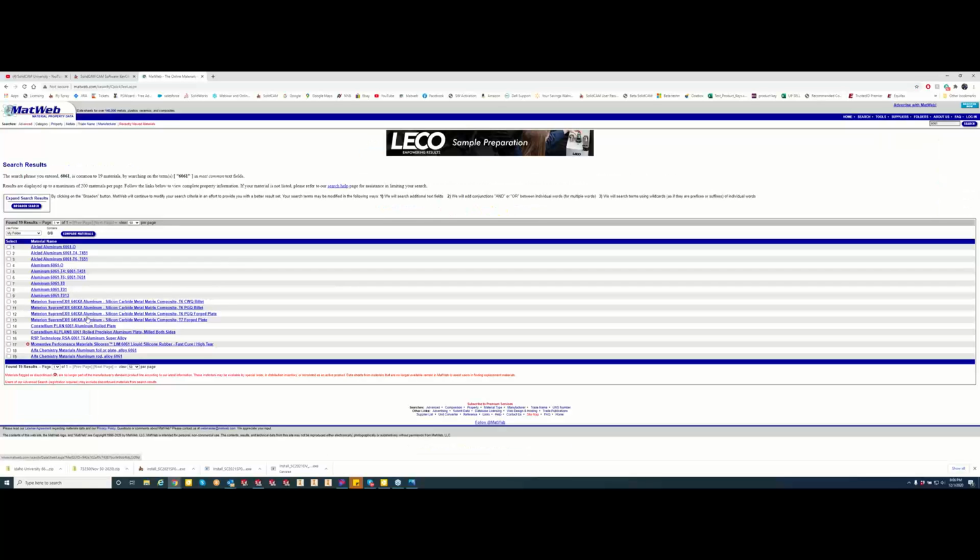This site will give you all the material dynamics that we're looking for in iMachining. Just for example, I'll do a 6061 here, and then we'll want to find the one that best fits it. So we'll do our aluminum T6 right here. So we've got aluminum 6061 T6. The variable we're looking for in here is the ultimate tensile PSI, which is right there. You can see we have multiple different temperatures, but the top one is the ultimate tensile PSI that we're looking for.